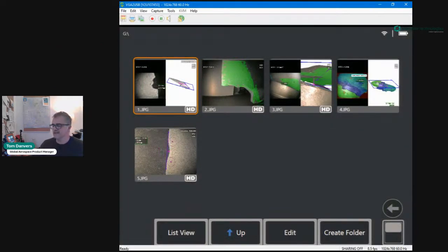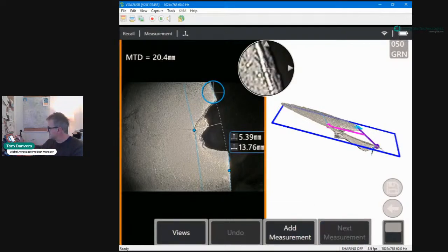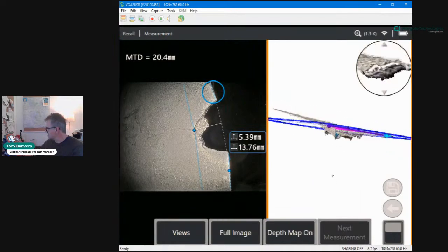So this is my Borescope screen. I've got essentially those 5 images that you saw earlier, but I wanted to take you through it with a little bit more time. So you basically had the introduction. If I load up the compressor blade nick, this is quite a nasty looking nick. I've chosen this example because you can see here, I've already applied the cursors associated with the nick.